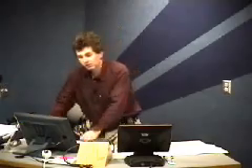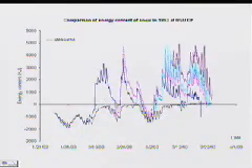Well, our observed energy content is measured with thermocouples in the snow. It's not really measuring energy content, it's measuring temperature. The energy content state variable accounts for the liquid water in the snow. So as soon as the snow starts melting, that's when the energy content is positive. The thermocouples are going to tell you that the average temperature is getting close to 0. Remember, this is an average of all the thermocouples.